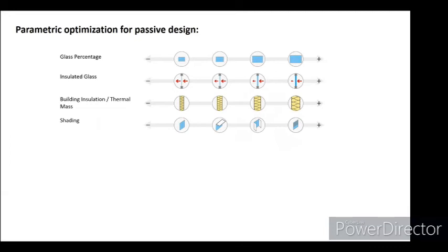So that's why in India we always push for high thermal mass, where it takes more time to heat up the wall. Before the heat comes in, it's already night and the outdoor air temperature is cooler. But the idea of insulation is more like a polythene cover. If you pour water or heat in it, it just stays over there. The amount of transmission through an insulation is really low. So in the Netherlands, we balance between insulation and thermal mass, but I think in India, we can put heavy thermal mass to create better comfort.